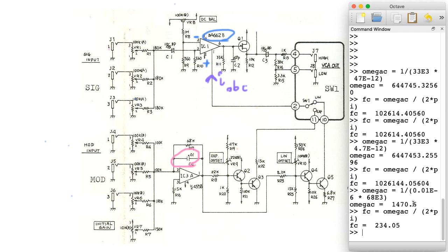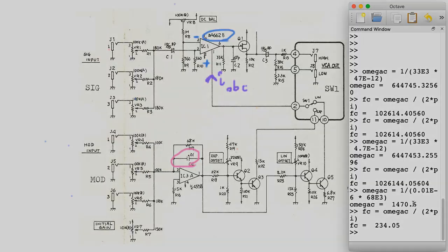So if you think about that from the standpoint of audio frequencies, that's a pretty low cutoff. But remember, this is intended for control voltages, and at least in this modular, they're not expecting those control voltages to vary terribly quickly. So the last thing I want to do here is to fade to black and justify my 1 over RC formula for the half power cutoff point.